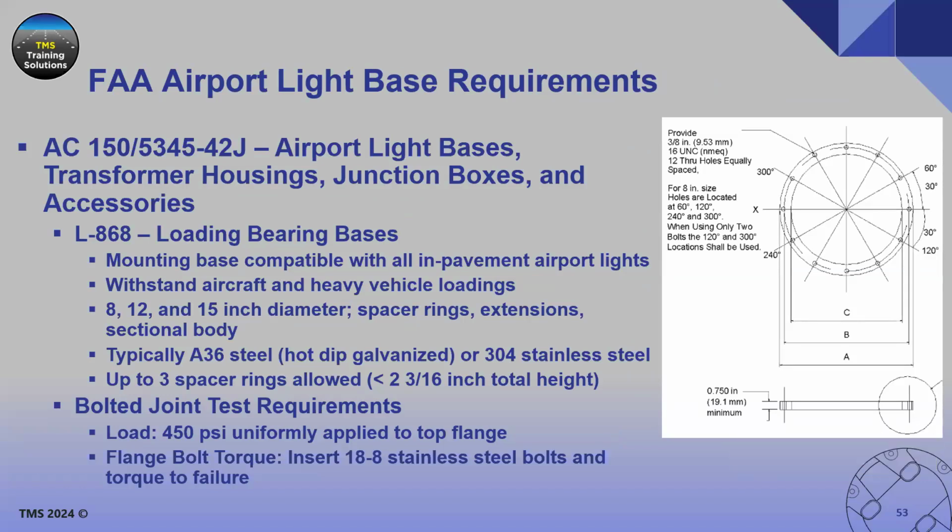So now that we're all up to date on our bolt knowledge and torque and tension relationships and how bolted joints work, I'm going to go through, in the United States, the FAA requirements for the other equipment that's in the bolted joint. So the base cans and the light fixtures and spacer rings. It's important to note that the FAA does not have any qualification or certification requirements for bolts themselves or for washers. So I'm going to go through the base cans and the light fixture requirements related to the bolted joint.